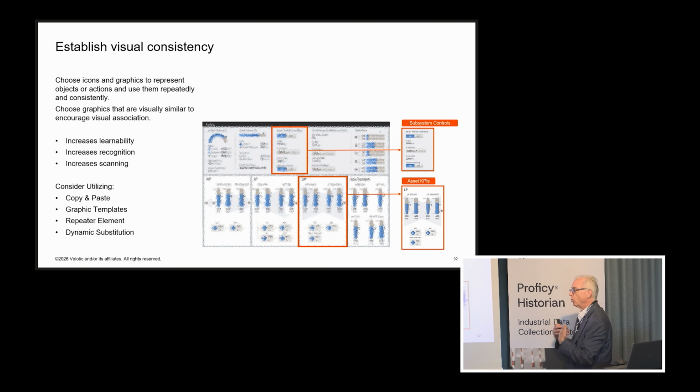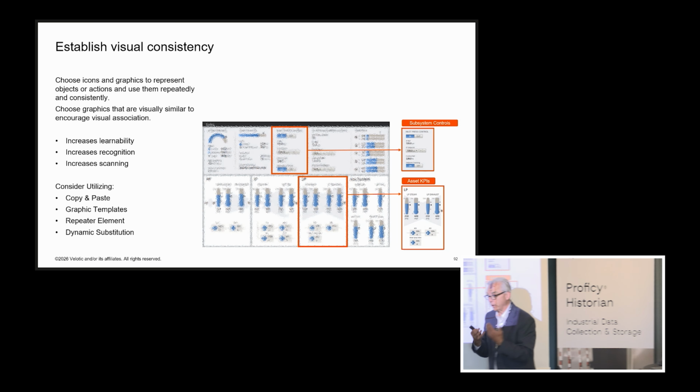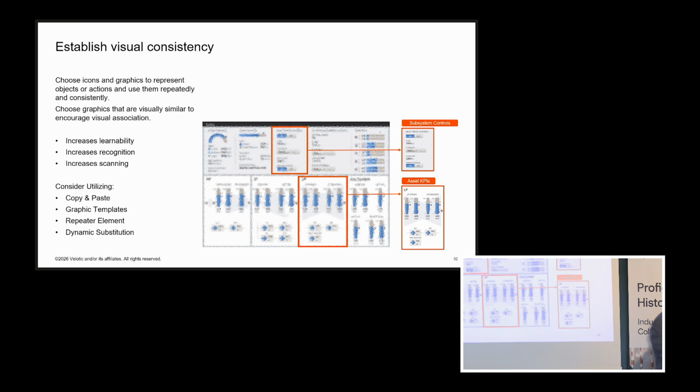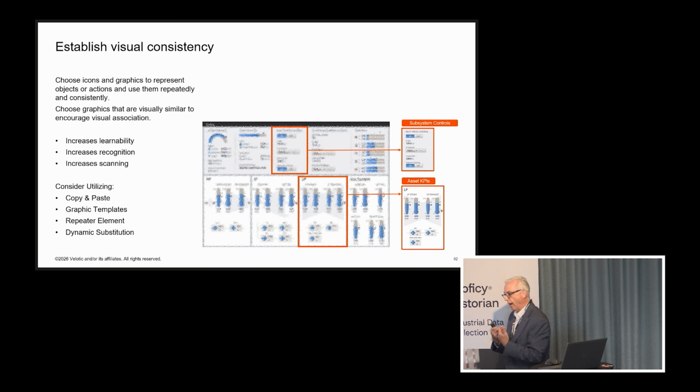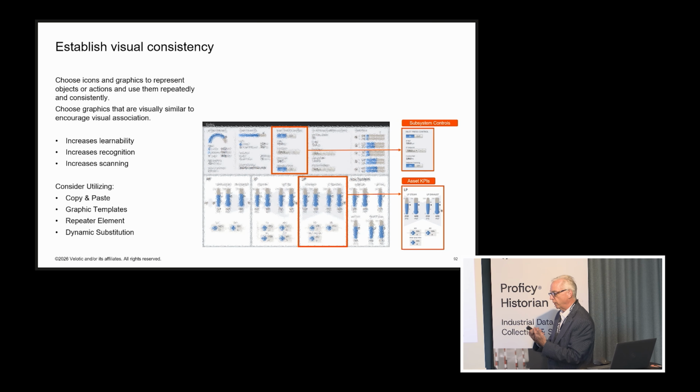So there's a whole science now around high performance HMI. And people think, oh, that's bringing screens up faster. That's not what high performance HMI is about. Yes, we have to do that too, right? We have done that. High performance HMI is how we improve the performance of the operator who's looking at the HMI screen by giving them the important data and bringing their eye to what's actually important.